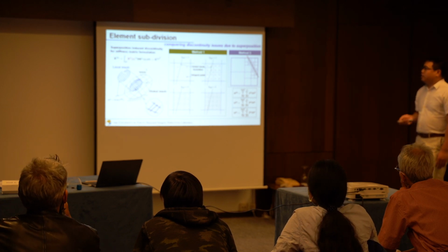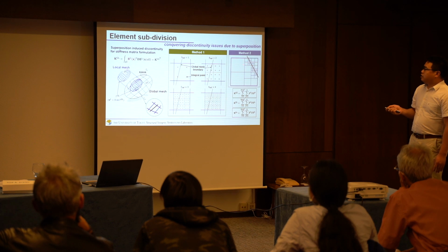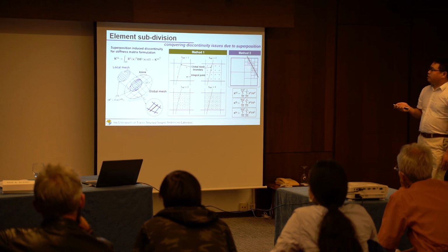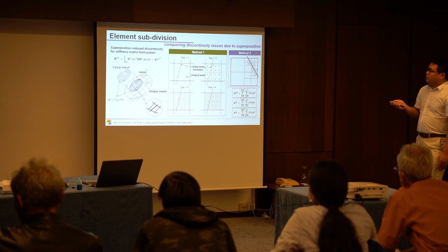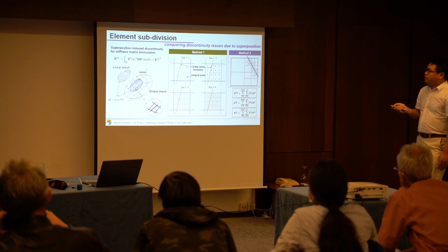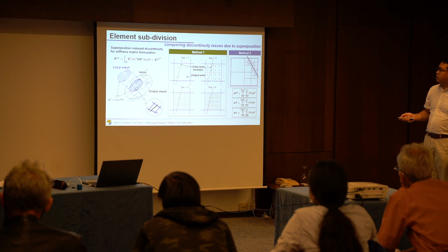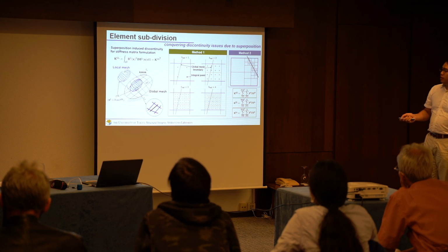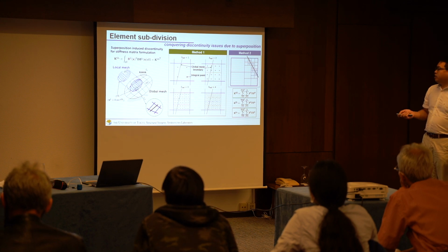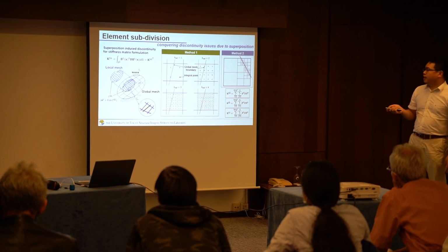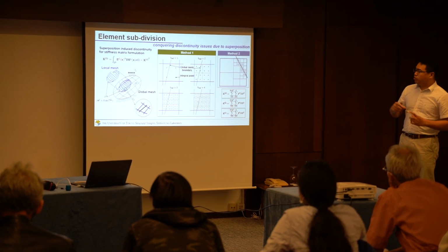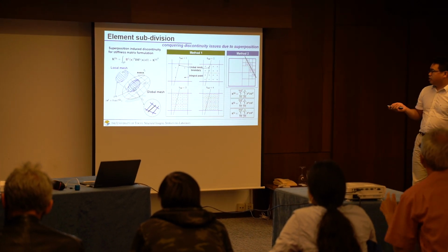Another method of subdividing the element is that we only enrich the sub-elements, leaving the discontinuity. In this case, we can reduce both the subdivided elements and the integration points. Then we can calculate the stiffness matrices KTL and KLL based on the subdivided element integration points. And for KTT, for an elastic problem, since the D matrix is constant in the element and the shape function only comes from the global elements, we have no problem calculating KTT.